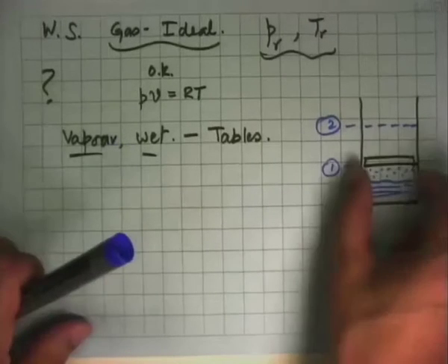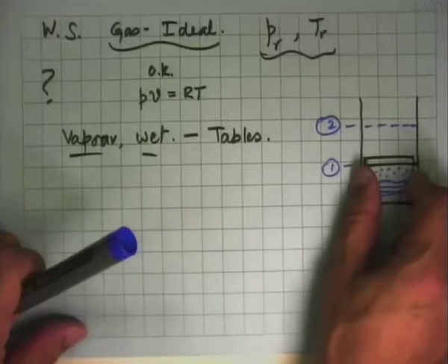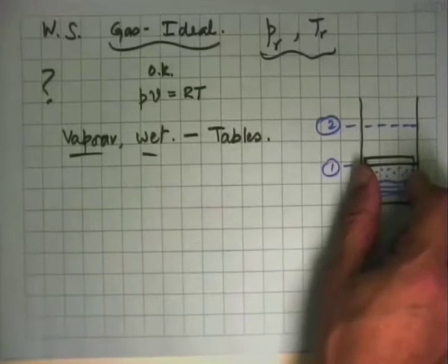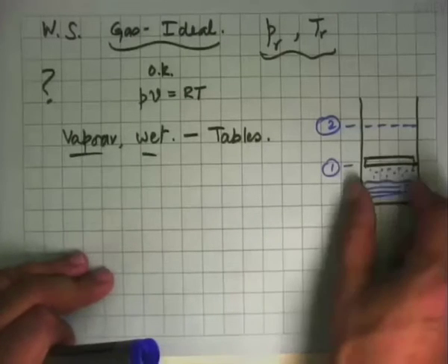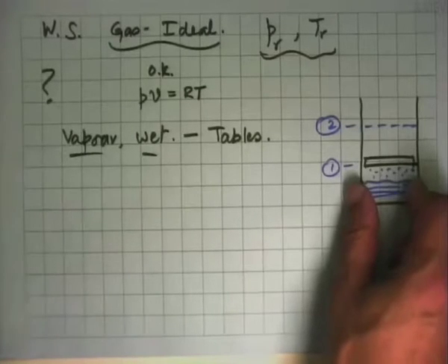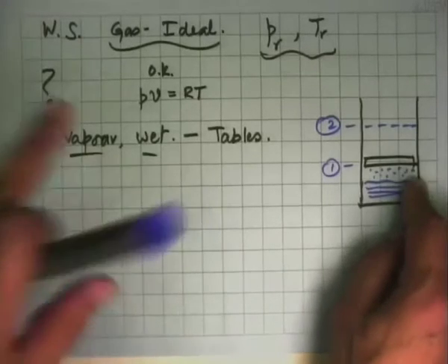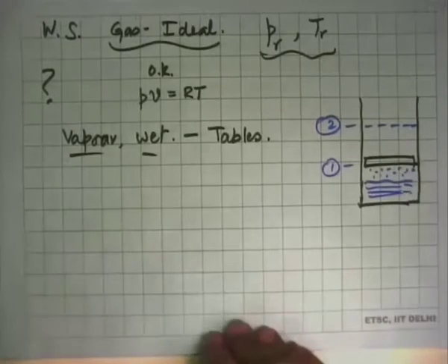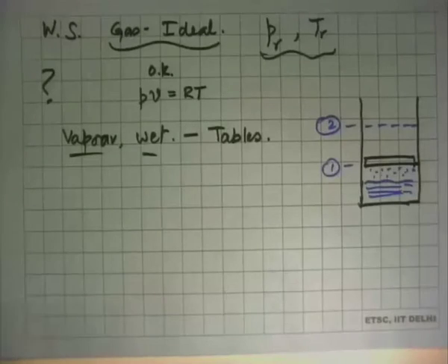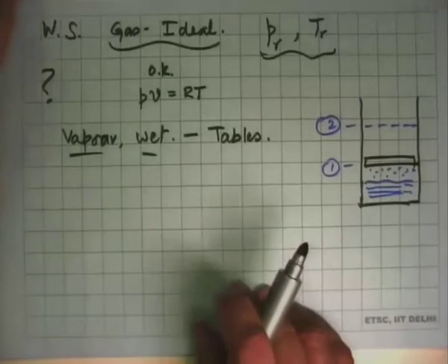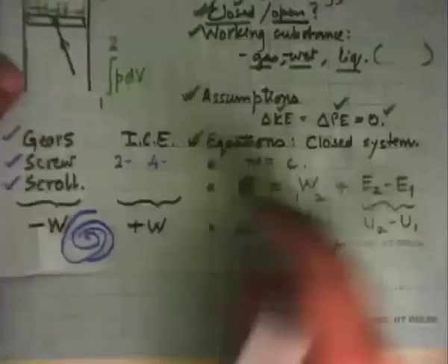If the problem says that a gas is contained here, and if by intuition we know it is nitrogen or oxygen at about ambient conditions or higher temperatures, the ideal gas assumption is really perfectly fine. But if the temperatures are close to the critical temperature or even lower than that, then we have to go to this route. Please keep that in mind. Okay, so that is the way we get the properties, and then we begin solving this problem and get whatever we want.